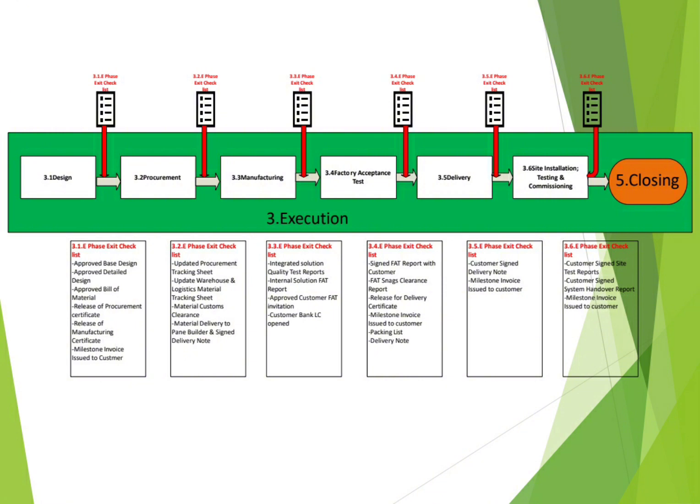There should also be a site activities plan in place with each activity, the duration of each activity, the planned start date, planned completion date, and after that 2 more columns for the actual start and actual finish, and the necessary remarks.